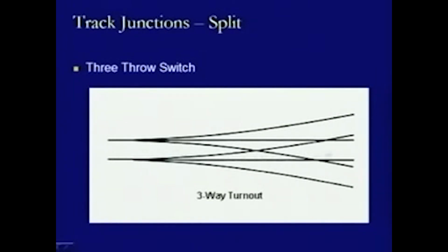then only we can define whether the train will be going straight or will be coming to this one with respect to this particular lead rail, because if there is a wheel on this lead rail and if the connectivity of this one is having a throw of switch, whereas this is being connected to this one, then it will go on the main track. Whereas if this is also being connected and this is also being connected, the other one also, then for this curved track, the train will be coming on this one turnout.